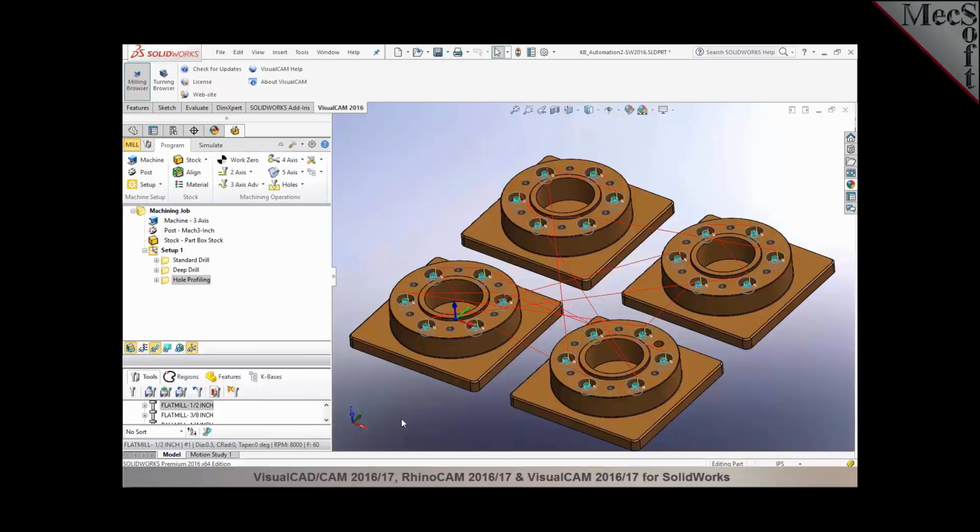Currently, when you save operations to a knowledge base, and if you have multiple machining operations, it basically saves the entire workflow of operations to a knowledge base. Now, if you'd like to save just an individual operation, one of the ways you could do it is you